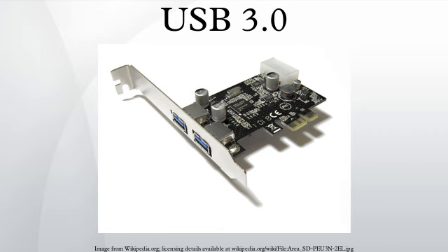Transfer speed: added a new transfer type called SuperSpeed or SS, 5 Gbps. Increased bandwidth: instead of one-way communication, USB 3.0 uses 2 unidirectional data paths, one to receive data and the other to transmit. Power management: U0 through U3 link power management states are defined. Improved bus utilization: a new feature is added to let a device asynchronously notify the host of its readiness.